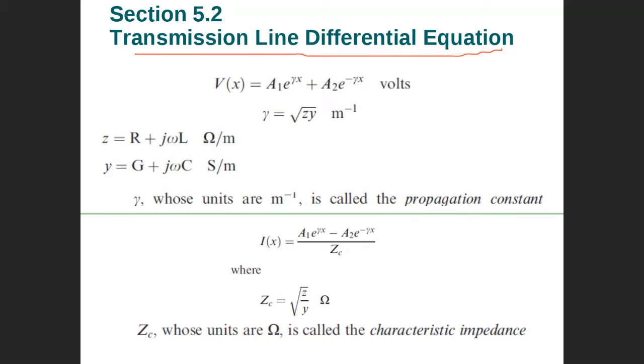Or instead of a short transmission line, we make it a medium transmission line. That's what we just discussed in 5.1. Medium transmission lines will be more accurate than short transmission lines, talking about the same system. Modeling the system as a short transmission line means you are maybe 2% or so off in your data.